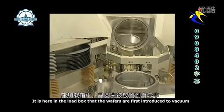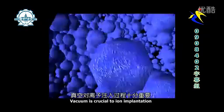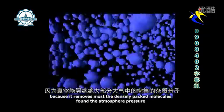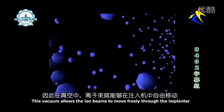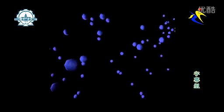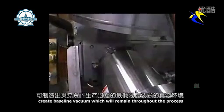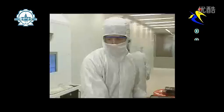It is here, in the load lock, that the wafers are first introduced to vacuum. Vacuum is crucial to ion implantation because it removes most of the densely packed molecules found at atmospheric pressure. This vacuum allows the ion beam to move freely through the implanter without colliding with unwanted atoms and losing momentum. A variety of roughing and cryopumps create a baseline vacuum which will remain throughout the process.